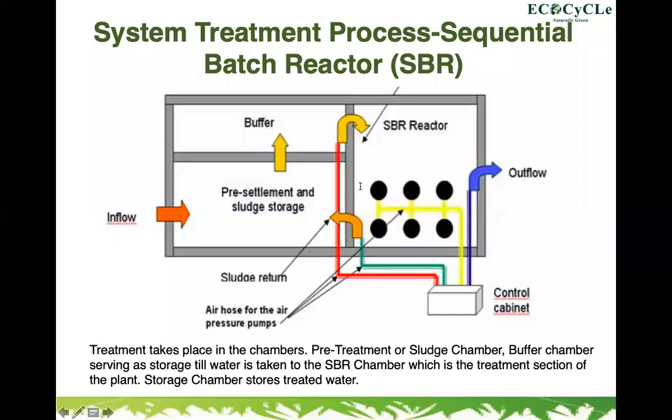And also we had mentioned the chlorinator kit. During the maintenance services, we also have to check the chlorinator kit because sometimes you realize that the chlorine has run out and the client has not checked to ensure that they have replaced it. So the only consumable we have in our system is the chlorine cartridges. Those have to be constantly checked. For a small home, we need one chlorine cartridge for a period of 4 months. So that is 4 chlorine cartridges in a year. So during maintenance, we have to check them.